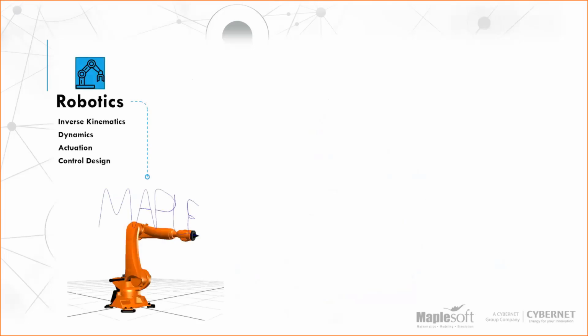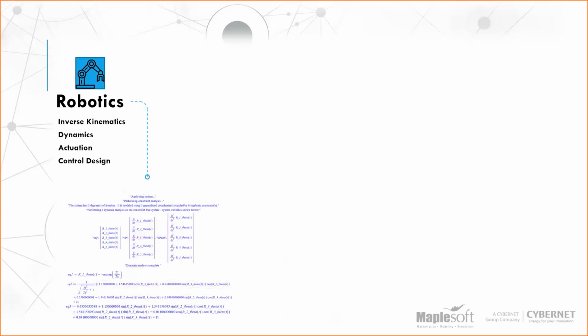So just an example of using Maplesim in different applications. In robotics, you can use Maple and Maplesim to get the equations of your robot, to do inverse kinematics, to analyze the dynamics of your robot, to consider the actuation for different joints, and also do control design. In this example, I've used Maple to get the multi-body equations of the robot, and solve for different variables to do the inverse kinematics so that the robot end effector would follow a predefined path.